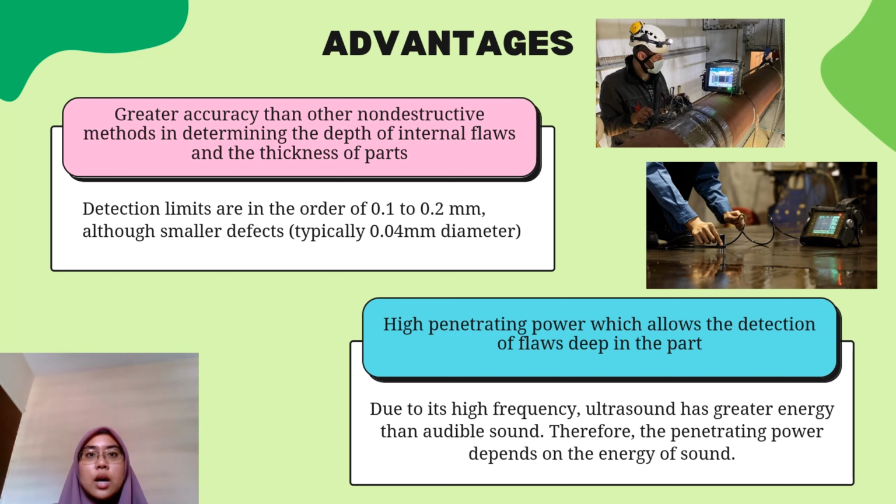The second one, ultrasonic testing has high penetrating power, which allows the detection of flaws deep in the part. Due to its high frequency, ultrasound has greater energy than audible sound. Therefore, the penetrating power depends on the energy of sound.